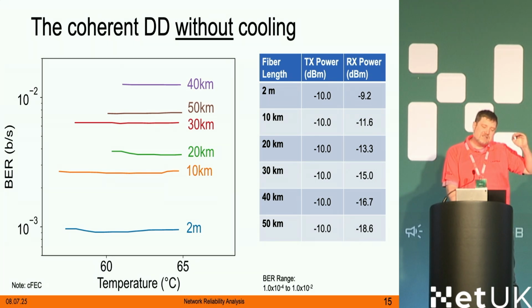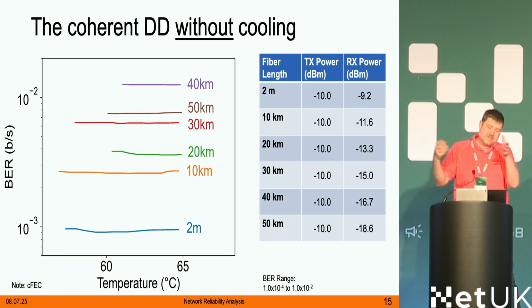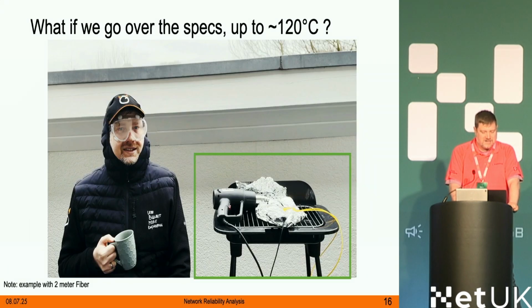The bit error rate is very dependent as a rolling average on how much data has been flowing, since it's this simple formula which just counts the erroneous bits and the number of total bits. So you are tracking the past the whole time. And without cooling, this was running for a couple of minutes because it gets hot quite quick. So you really have to cool down these.